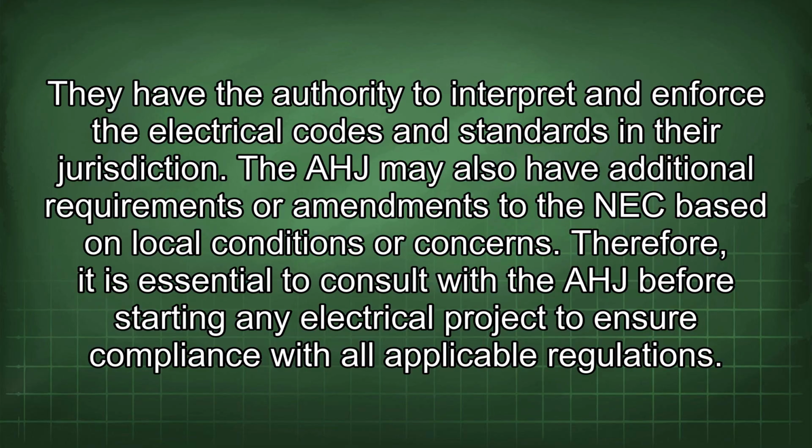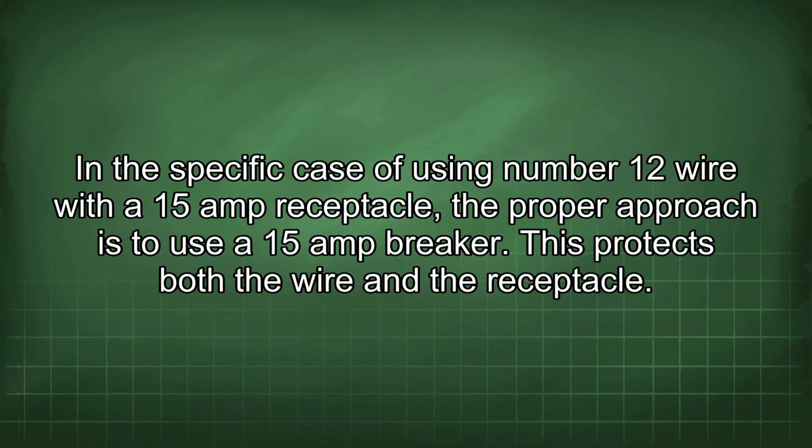Therefore, it is essential to consult with the AHJ before starting any electrical project to ensure compliance with all applicable regulations. In the specific case of using number 12 wire with a 15 amp receptacle, the proper approach is to use a 15 amp breaker.